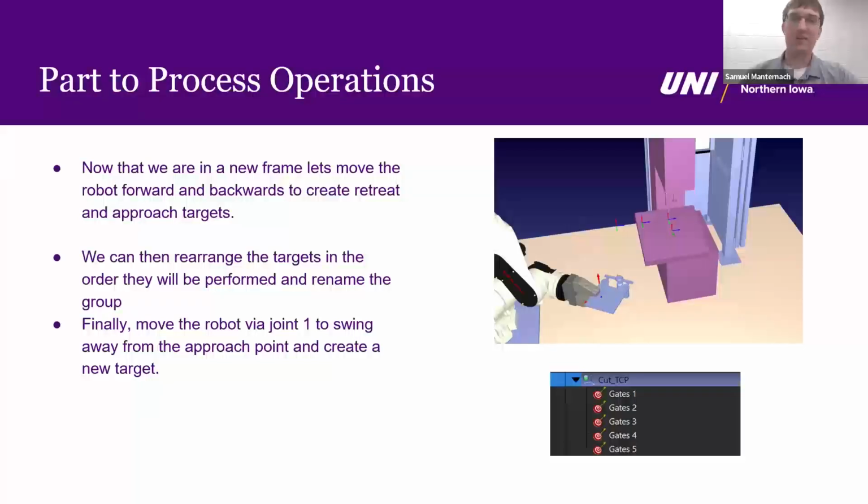By creating that target there, we know roughly where we're going to start, so we can start moving at a slower speed when we know that we're near our bandsaw blade. Beyond that, we're also going to move even further back. I'd recommend doing this simply by using your dialog box on your robot, or you can move it in the negative Z direction to get away from our bandsaw blade and keep everything in line with that bandsaw blade as we're approaching the blade itself.